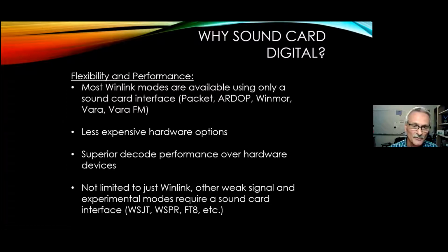They also seem to have superior decode performance over hardware devices, and I'm talking specifically about packet radio. When we compare a hardware TNC against a Soundcard with a software TNC application, we are pulling packets out of the noise and decoding them where a hardware TNC would ignore the packet altogether.